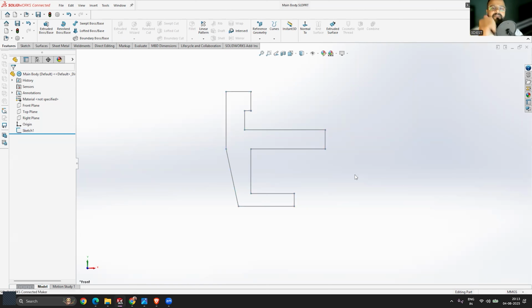Now, what is 3D? 3D is just an extension of a surface, right? Once you take any surface and extrude it, or add a direction in Z direction, add a material in Z direction, it will get converted to 3D, right? So paper is 2D, but if you stack multiple layers of papers in Z direction, it will become 3D, right? So 3D always starts from a surface that should be closed from all sides, right? If it is open, then that is not a surface, that is simple boundaries, right? So it's important that you create a closed profile.